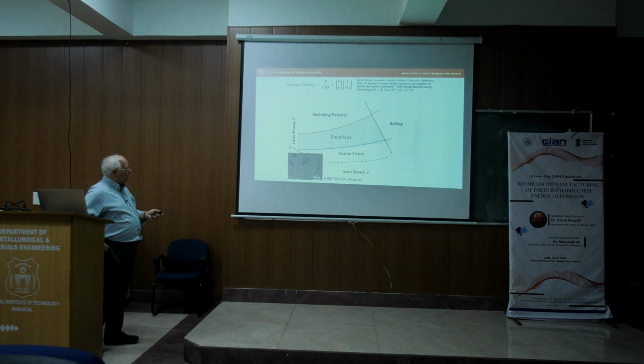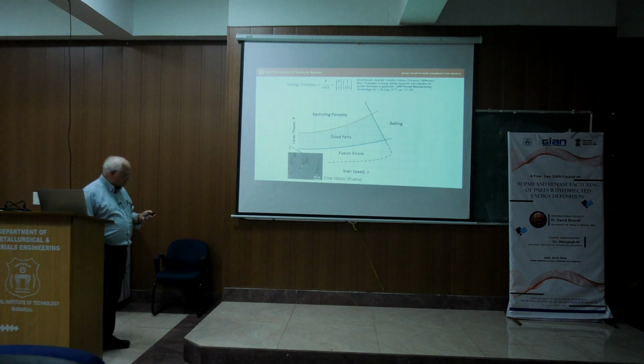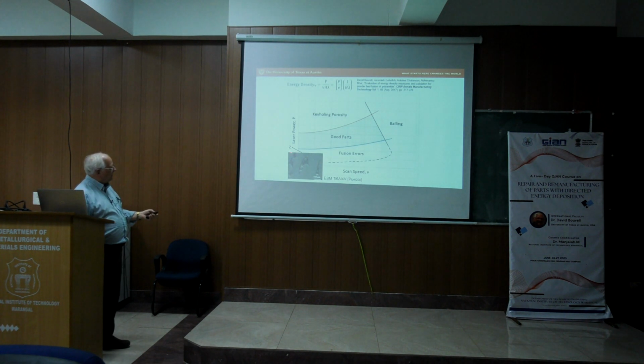All right, so here are some micrographs of what these various regions look like. You have to appreciate in this one that the Z direction is this way, so here are the layers, going almost vertically. There's just not enough power to completely densify and melt everything, so here's some of the feedstock powder.